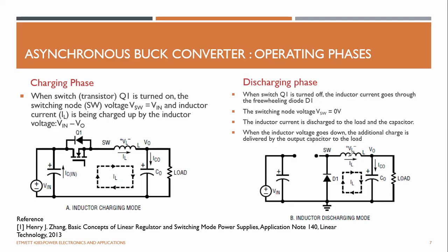And now, you know, the inductor always tries to keep its current circulating. Inductor current cannot be changed instantaneously. So the inductor is looking to circulate its current because it cannot stop its current. So it can pass this current through this capacitor as well as the load. Now the returning current can come through this diode, because it cannot go through here, because there's a bridge here, right? So it can't return from here.